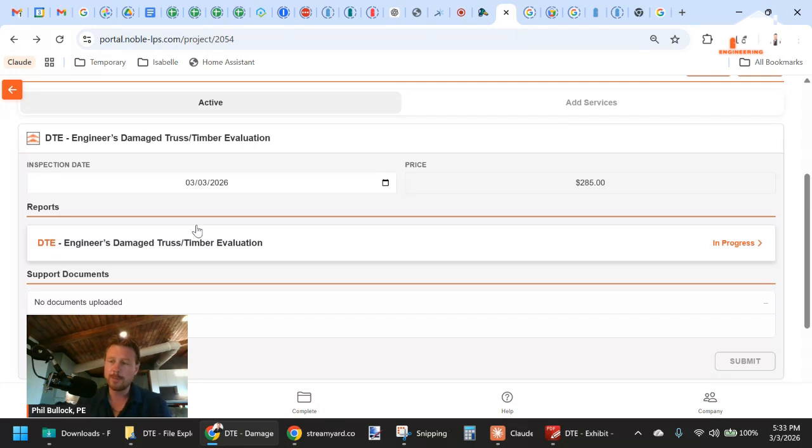And providing a fix is probably maybe 20% or 30% of our DTEs right now. Most of the DTEs that we get requests for are modifications made to the construction in the attic, some things that were DIY, cut members that, okay, they cut a member, but we still don't think that it's a structural integrity problem, things like that.